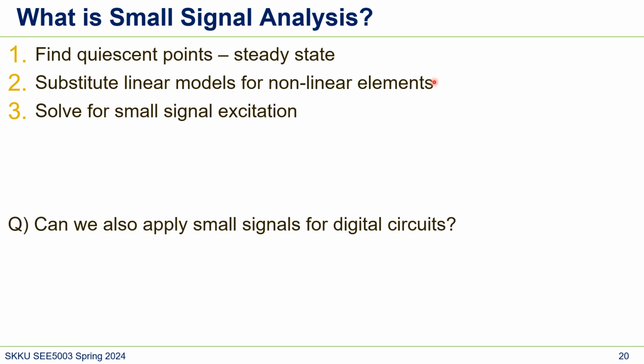But in most analog circuits, do you think the operation region of the MOSFET changes? No, it doesn't. It's just stuck at a single operating point. I'm not saying every time, but a lot of the time the MOSFET stays in a single region. In that case, capacitances are kind of constant.